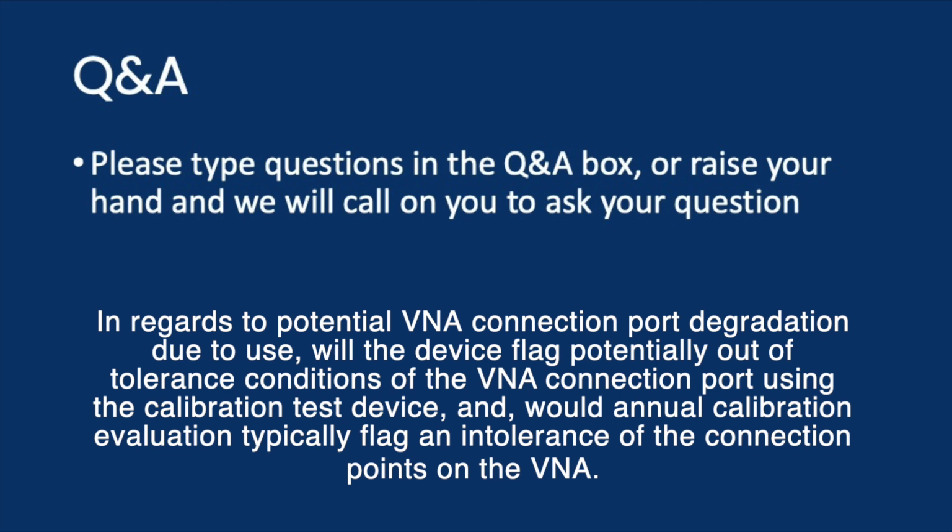Yeah, the annual calibration would definitely do that. I think that's part of the calibration process. They'll actually examine the ports of the device in terms of measurement tolerances, make sure that the internal pins at those connectors have their proper dimensioning, as well as just visual inspection to make sure they're okay.